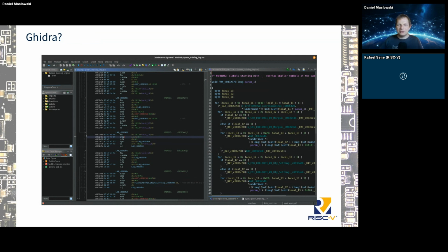The question here is now, how do you actually dump the mask ROM? That's an excellent question. So, a very simple technique is, if you already have, let's say, U-Boot running on an SoC, then you can enter the U-Boot menu, right? And then you can start typing things. If you know the base address of a mask ROM, then you can read that mask ROM from that base address in memory. You just need to provide the size, and you can copy that to somewhere else in memory, or you can also just push that out over TFTP, for example, or write it to a USB drive or an SD card or something like that. So that is one way to go.